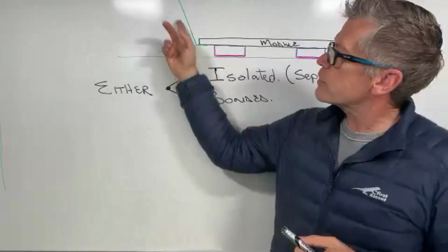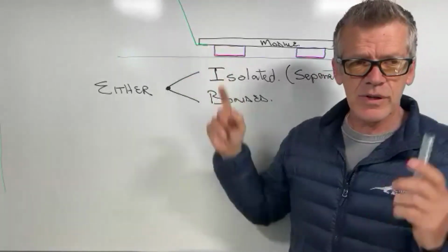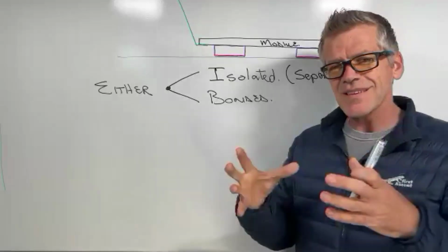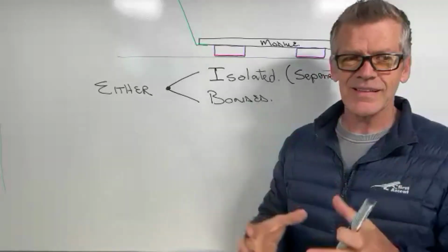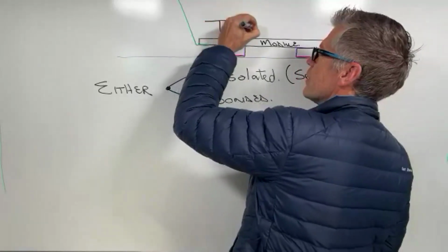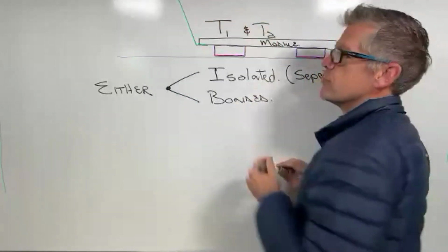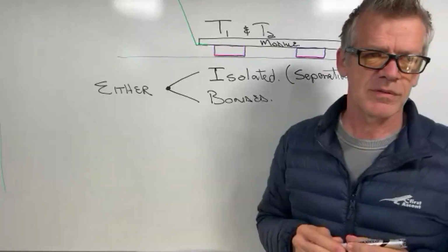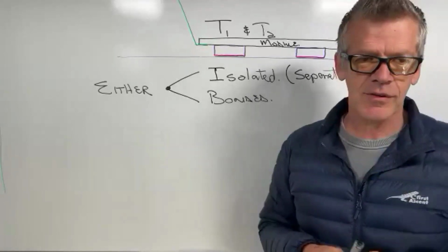Okay. So now you are forced. Because they've put these air termination rods in, it means that they are expecting lightning. And because they're expecting lightning, this forces them to put in type 1 and type 2 surge protection equipment. Yes, theoretically, yes. Okay, give me the practical side of the conversation.